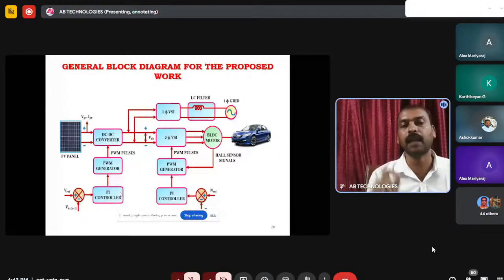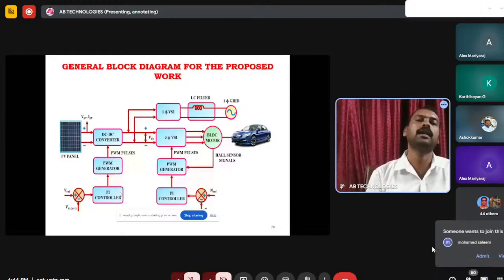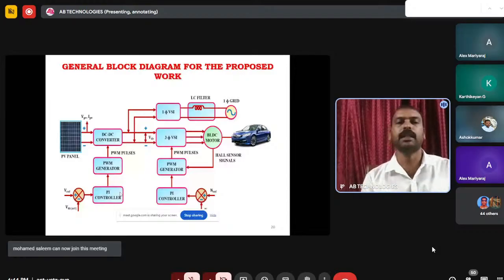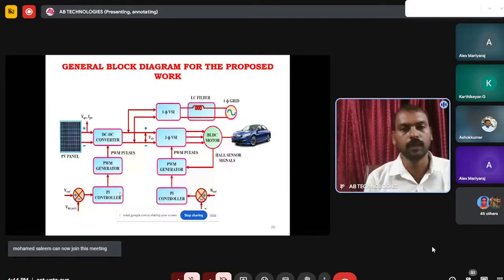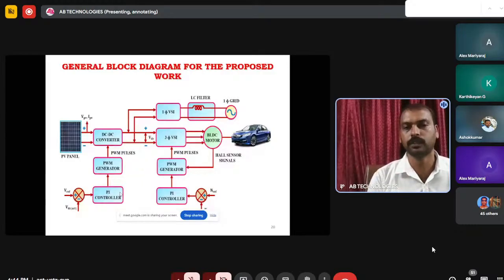And it is the underdamped system, also a second order underdamped system. So it's creating maximum peak overshoot issues, rise time, fall time, settling time. After 0.5 or 0.7 or 1 second only, the voltage will settle. Before that, 10 to 20% oscillations will be there: 330, 350, then 200, 250. After that only it will come to 300 volts. So it's creating maximum peak overshoot issues simply.